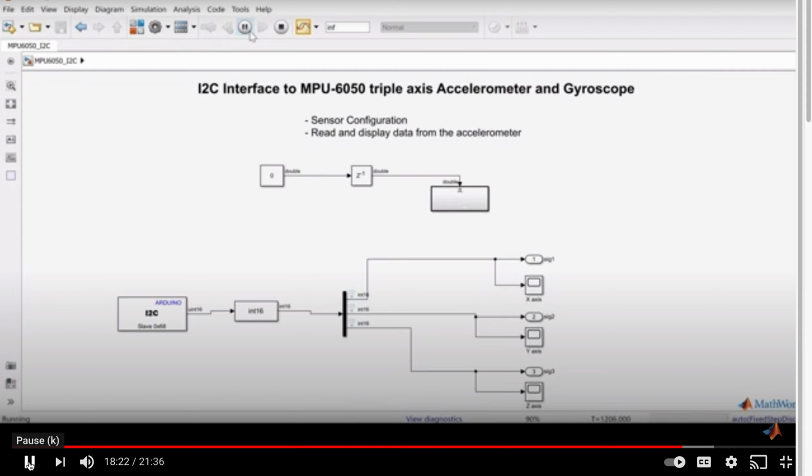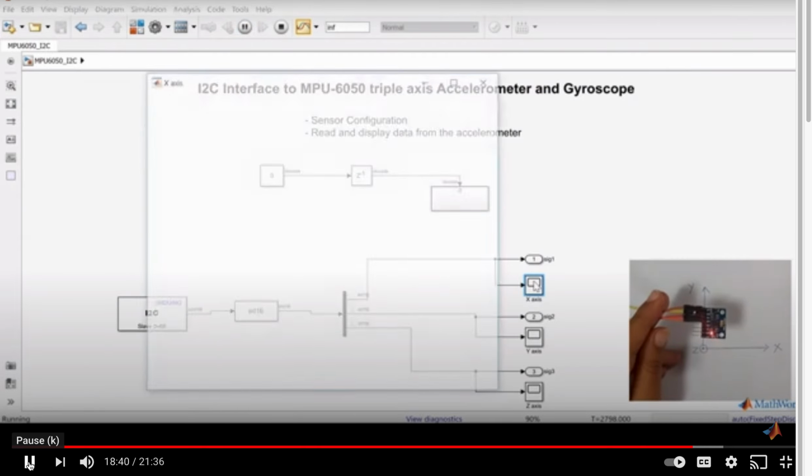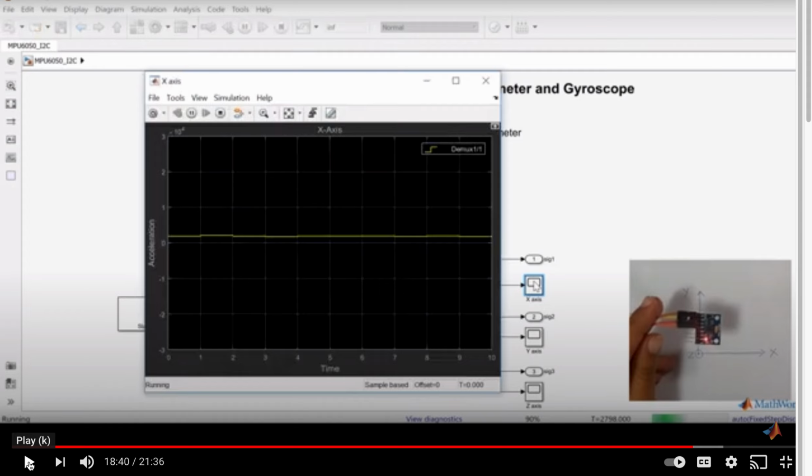We will keep our sensor still and point the axis in the up and the down direction. Then the only acceleration that the sensor would sense would be due to gravity pulling it down. Let us try moving the x-axis. Now, just remember how this works. As I explained last time, the soldering that you see over here is in the direction of y. Okay, so orthogonal to that is x, and z is pointing up and down.